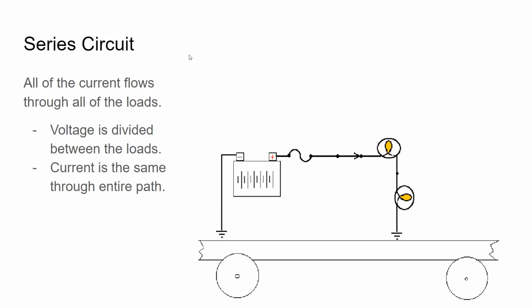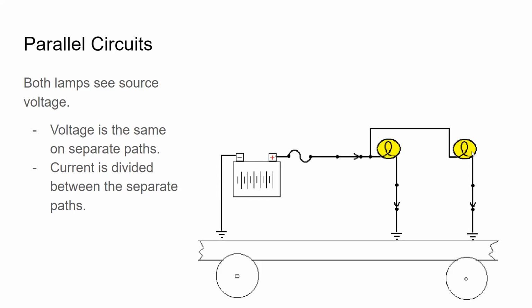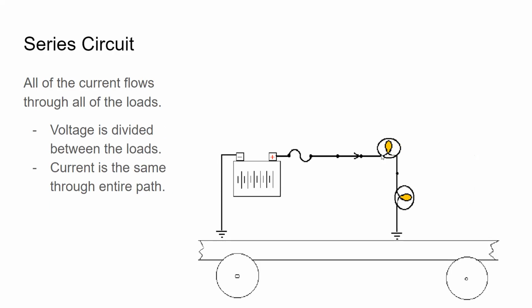All right, so now we're going to talk about a series circuit really quick. So our power source is the same, 12 volts going through a fuse, through a switch, and now we've got this bulb and this bulb, both pulling on that voltage. They're twinsies again. They're the same bulbs that we had here in our parallel circuit. Notice how in the parallel circuit, these 2 bulbs are a little bit brighter. And in this example, they're not quite as bright. They have kind of that soft orange glow going on.